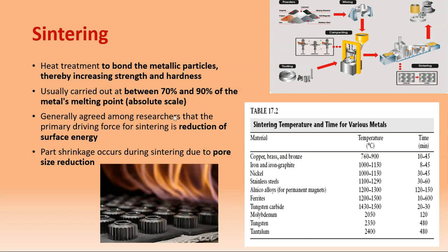Okay, do not exceed the melting point. Usually during the sintering process, reduction of surface energy and part shrinkage will occur due to the pore size reduction during sintering. So these are the proper temperature and time for the different materials.